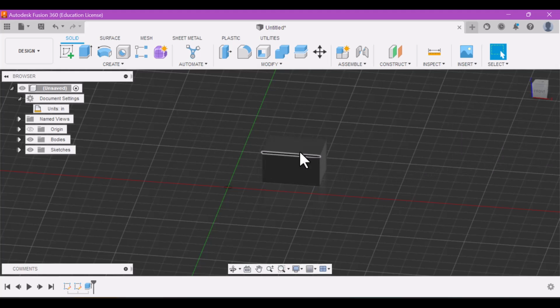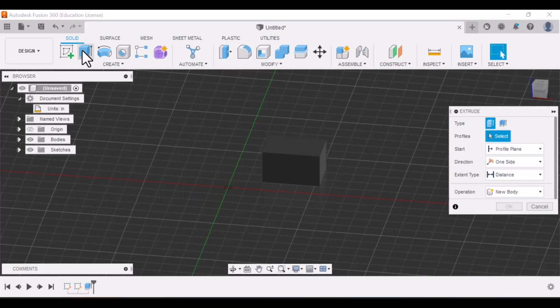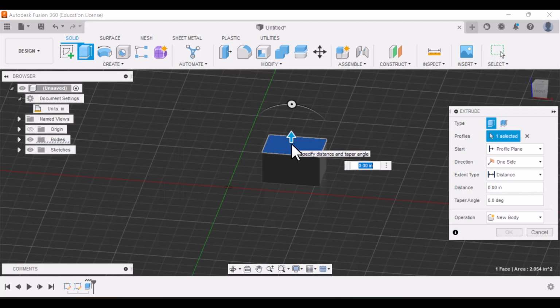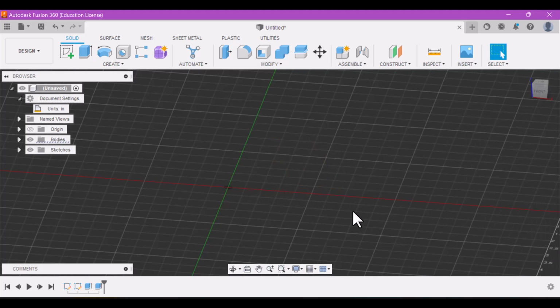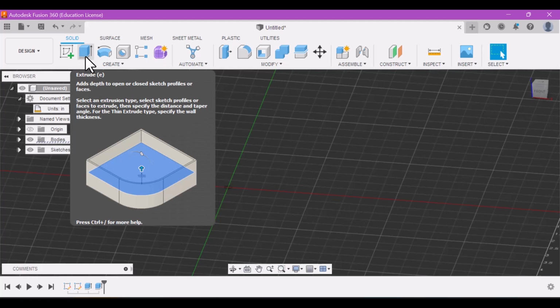So we were able to extrude this upwards, but say if you wanted to extrude this downwards, for example. So you're going to hit extrude again, we're going to tap the top there, and if you want to go down for extruding, you always want to hit a negative. You put a -1, and now suddenly the arrow goes down, it shows red, and voila, we got nothing, right? But often you will be using different ways to extrude, upwards, downwards, and there's an option actually for going both ways. So quite a basic function, but you can do a lot with it.